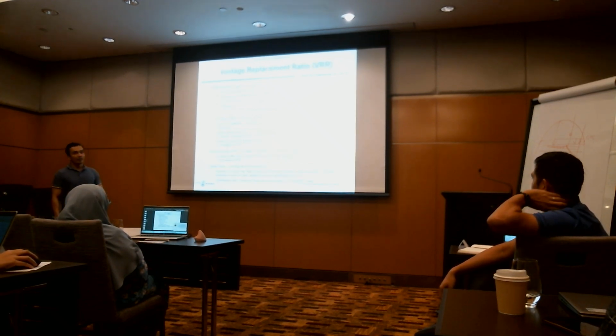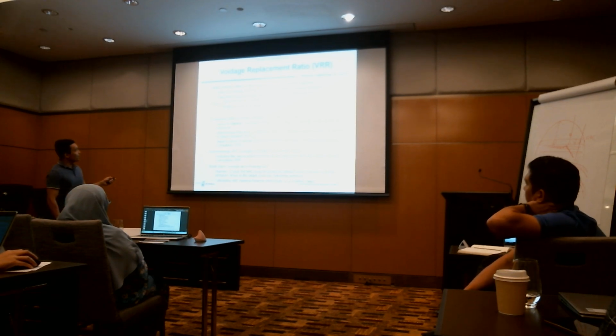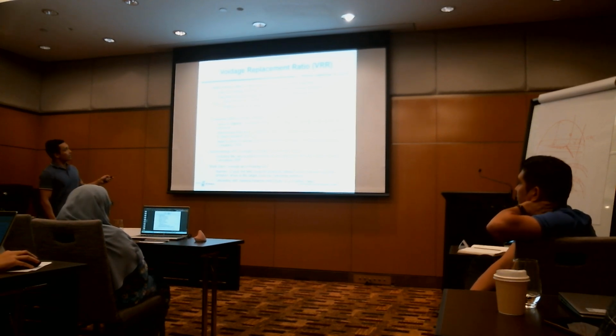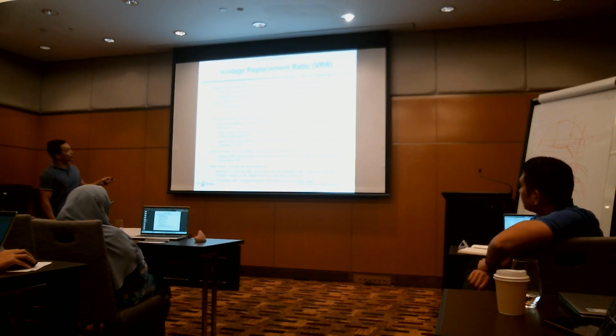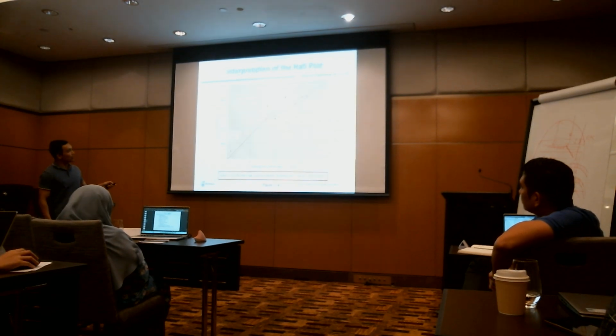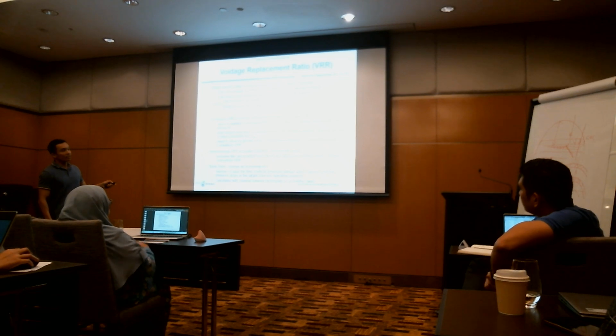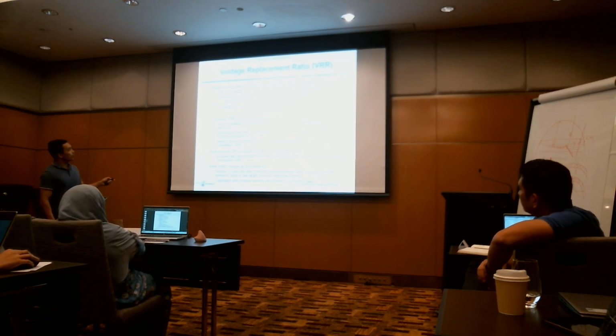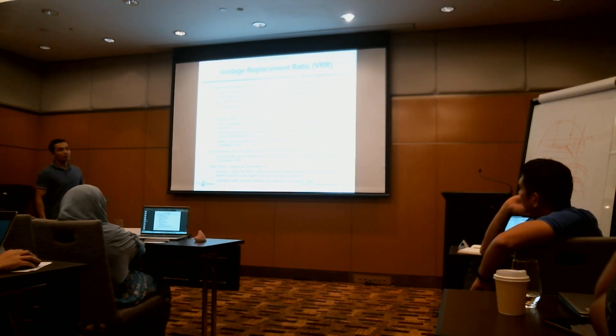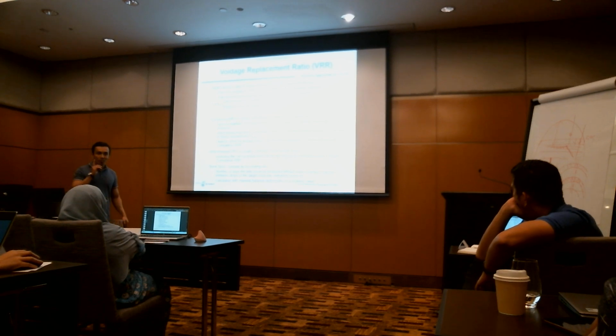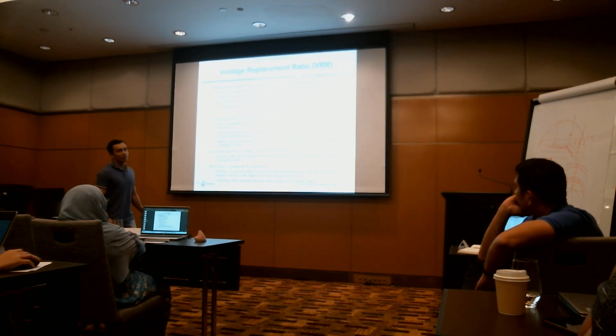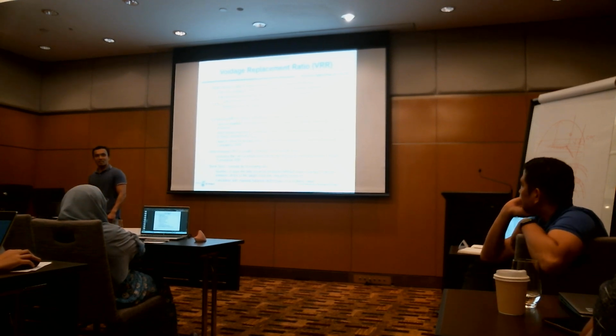Okay. Remember, I said earlier, VRR, voidage replacement ratio. It's just injected reservoir volume over produced reservoir volume. It can be the oil you produce, water, and also the GOR. So VRR, ideally, if you want to maintain the pressure, what do you expect the ratio to be? 1. Yes.